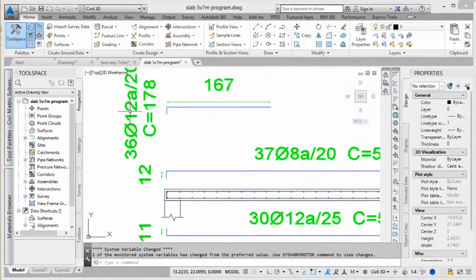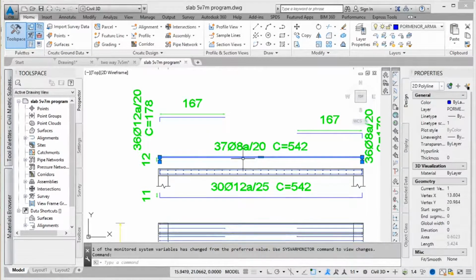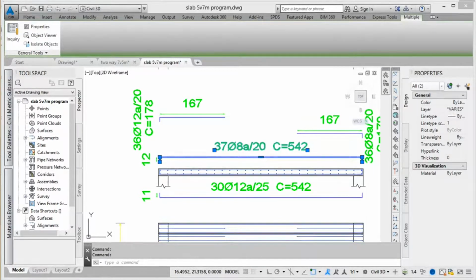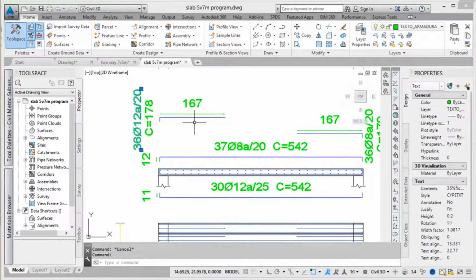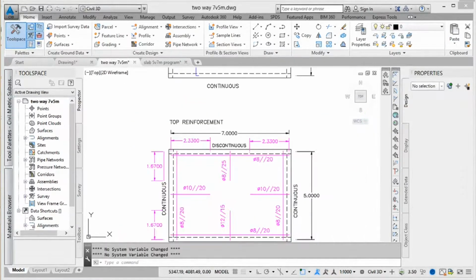And it considered a diameter of 12 spaced by 20, but there is one thing that this commercial software considered, that is the combination of factors. So here on the top, it always puts some bars all the way, the minimum steel, a diameter of 8 spaced by 20, which in our calculations we have also considered as the minimum steel. So we always put this. So this is going to affect this one on the corners, because now there are 2.